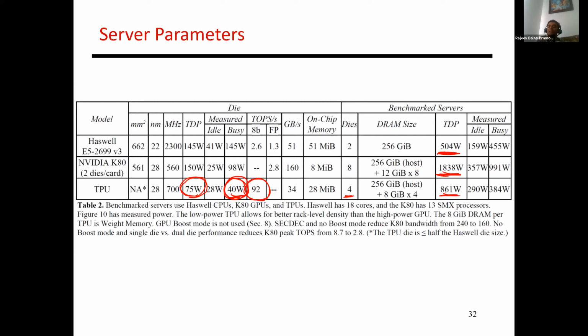I did come across Amazon announcing their new chip for this. It's called the Amazon Inferentia, and that does have support for spatial multiplexing, right? They break up their compute engine into smaller units. So you could have 8 units, and these 8 units could be split across, let's say, three deep networks running at the same time. So the Amazon chip does have support for spatial multiplexing. The Google TPU does not.